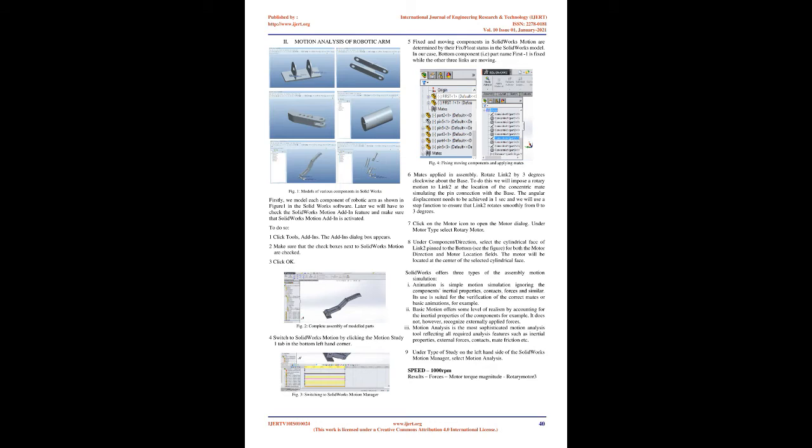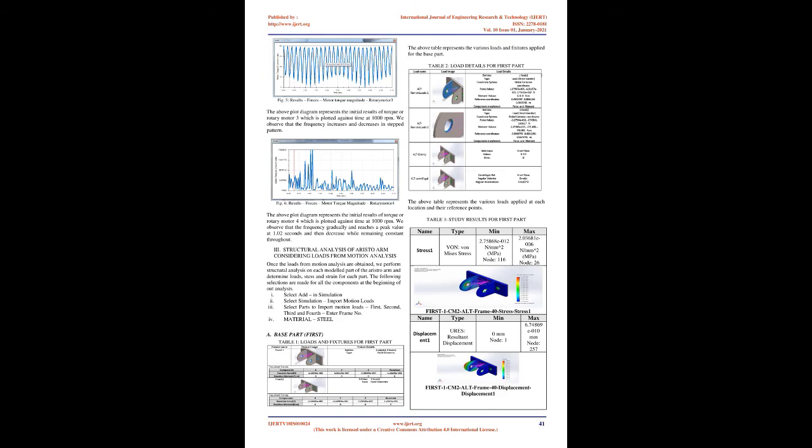10. The humanoid arm consists of 6 RC servo motors, main controller board and a mechanical structure, and its trajectory is generated using geometrical analysis. Here total length of robot arm and angle of rotation are considered at each joint. To get the required position provided by the user, each joint moves in such a way that an optimal motion path is generated.